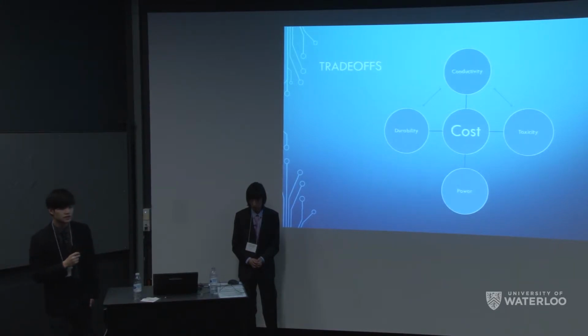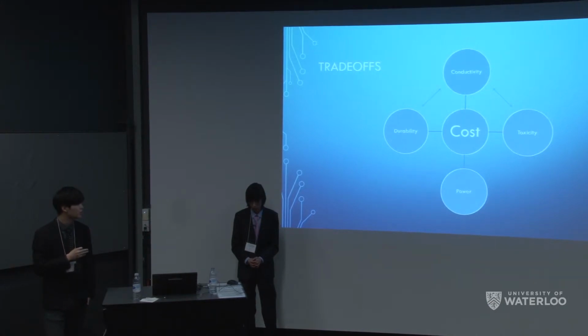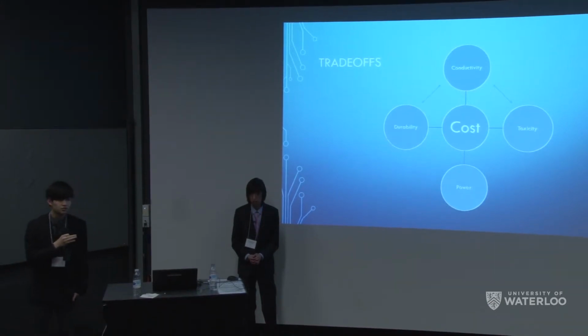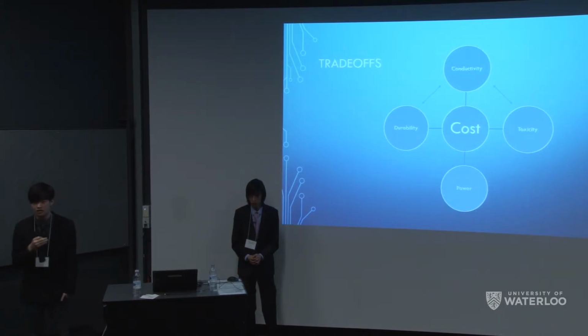The other three on top talk a little bit about the silver powder. The reason we chose silver powder mixed with a little bit of lead solder is that we needed conductivity to be similar to the copper currently used in PCBs, and the oxide of the metal would also have to be conductive. In terms of toxicity, we use silver because it's non-toxic. It may be harmful if swallowed, but people won't be ingesting the silver. It can be handled and washed off if accidentally touched. We are dealing with microparticles here, just to clarify.